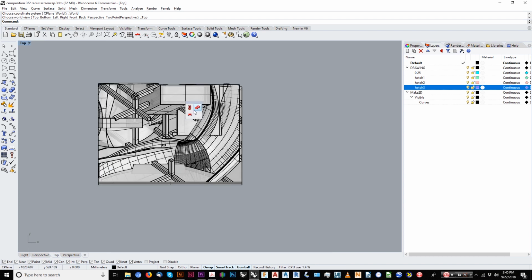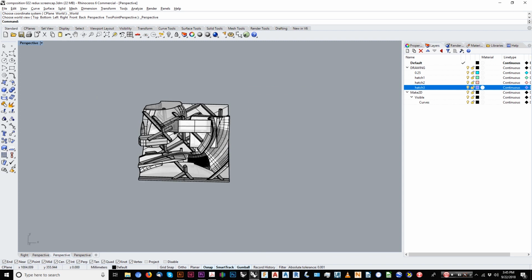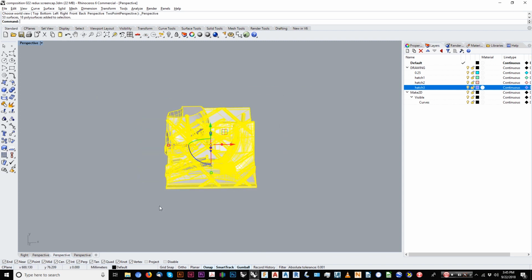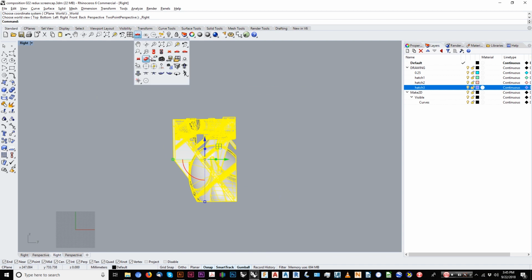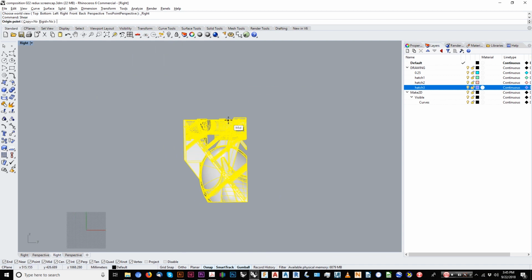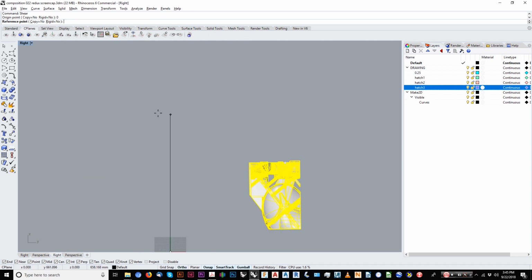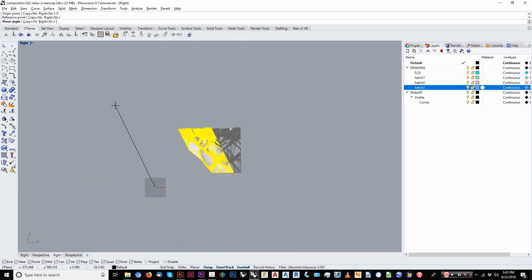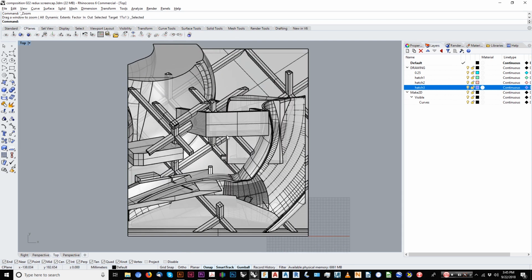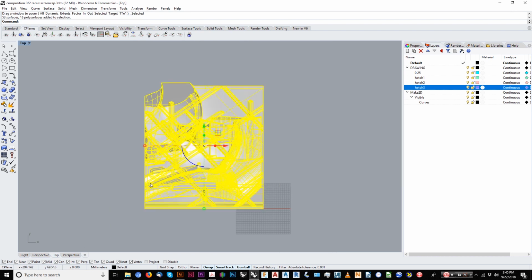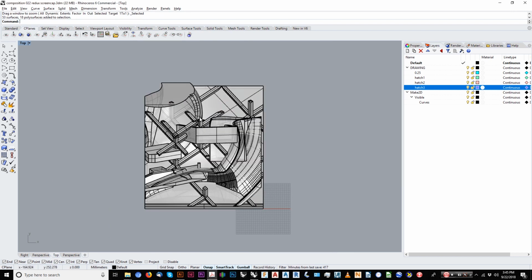So in order to start, what we'll do is you can set your side view here also. We will use the shear command, and we set 0, and then we will shear it so that about 20 degrees. That should give us a nice look. So hopefully that's the same angle that we've used in the past. What we'll do now is we'll just make 2D to get the base drawings.